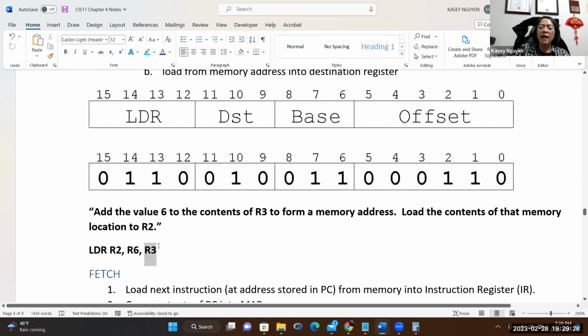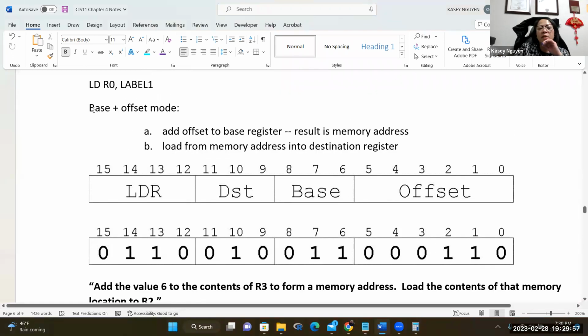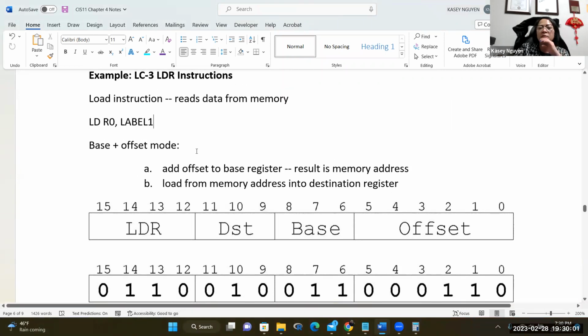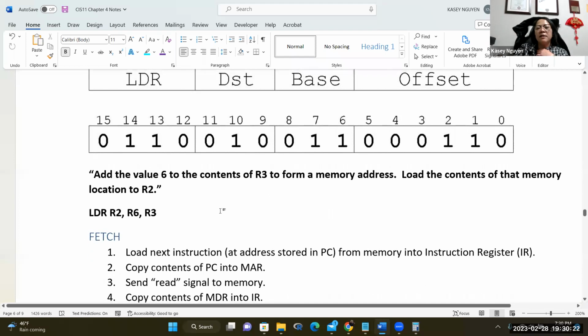In the prior line, we will likely have to have register 3 loaded with an address. Then we would do an LDR. I normally don't like using LDR because that's an extra line of code, where I have to load to another register to load to another register. In order to use LDR, you have to preload the other registers, these operands, to be loaded to the third register. So I would rather just load from the label and fill the label with the value. Direct load just saves time, but if you have a reason to use LDR, you can. You're going to see in my example programs for the lab that we mostly use LEA, LDI, and LD. Otherwise we have 2, 3 extra lines to load and it just becomes more complicated, so just reduce the work.